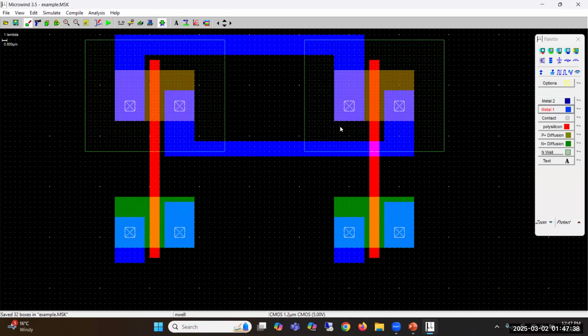So again, let me use this manner. We have done the gate connection, the source and source of PMOS, and drain and drain of PMOS. Now let's do this one. What is this one? Both the drains of PMOS are one node now. So this is the drain of PMOS, and this one is the drain of NMOS, the NMOS that is connected to the first PMOS.